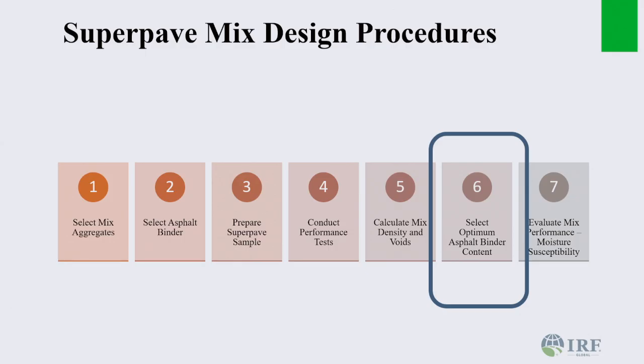Yesterday, Prof talked about 5 or so. We will normally start even below that, 4. So you start with 4, 5, maybe 6, different binder contents with different mixtures, and then determine the optimal. Maybe your optimal may be 4.5 or 5.5 or 6.5 or whatever, 7.5. That will be your optimal binder content.